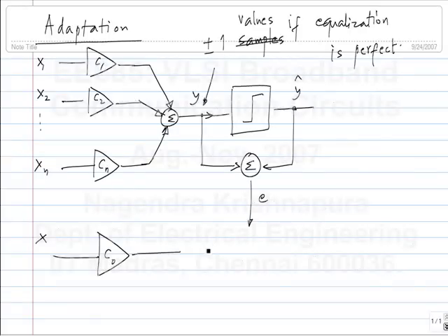And of course the point here is that the X1, X2, the entire sequences are not known in time. You need to be able to update the coefficients as the inputs come, and over time the coefficients should adjust themselves to the right values. Right values meaning again the values that give you the smallest mean square error between the actual Y and the desired values of Y.